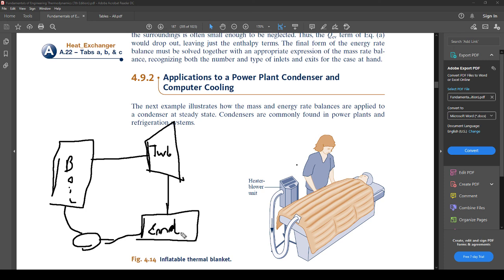And so it condenses. Most power plants have their own water supply, like the one in Lake of Egypt, which has its own man-made lake that it runs this with right here. When it runs through here, it does heat exchanger passes with a bunch of tubes, and essentially the condensate, which is why it's a condenser, falls out. The condensate leaves. Here it's still high temperature, so T2 is still pretty high. Pressure 2 is low. It's as low as it's going to get in the cycle, probably close to atmospheric pressure.